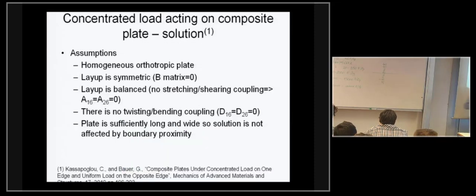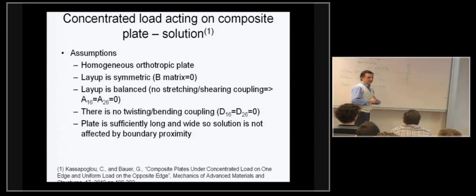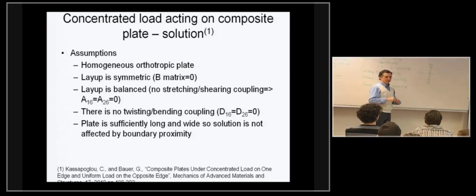These assumptions reminded me of one thing I wanted to say. I keep mentioning quasi-isotropic, and just for purposes of definition, it's also in the text in the book. One way to create quasi-isotropic laminates, or the best way to create quasi-isotropic laminates, is to make sure that you have exactly the same number of fibers in every direction.